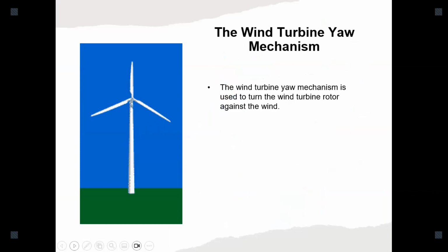Actually, this is the point, maybe Nalim's question here. The wind rotor can yaw like that. We call this yawing. Generally, this wind rotor can yaw. This yawing is done by detecting the wind direction. There's a sensor on top, generally a wind vane there. If you look very closely, some modern turbines use different technology. Not only the wind vane, there are different high technologies people are using there. Sometimes maybe the torque and unbalanced things. A lot of techniques, a lot of algorithms, are used to predict wind direction.